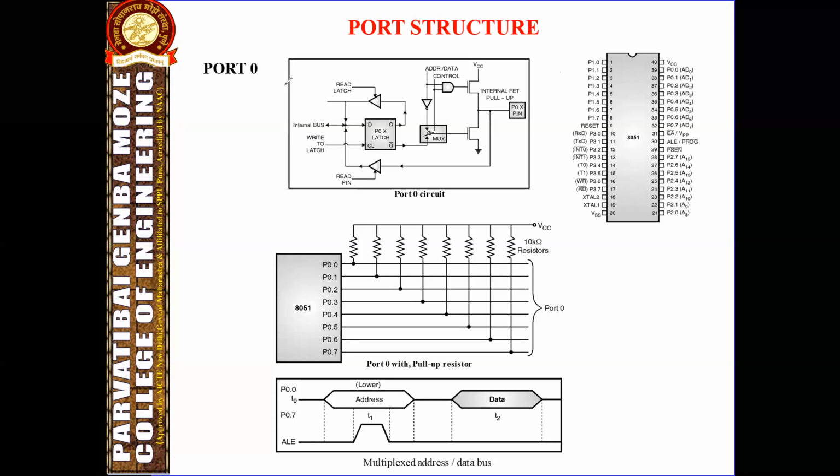So, port 0 structure. Here, port 0 is a multifunctional port of the 8051 microcontroller. It can be used as a simple input-output port, or for generating the data and lower order address bus for the external memory. The figure shows the port 0 circuit. Its address is 80H and it is a bit addressable port.